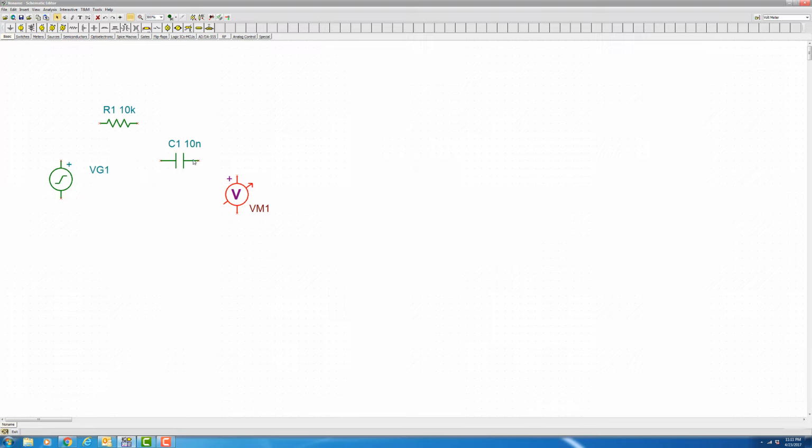It uses the last value that you picked, and I happen to use these for my tutorial, so I kind of cheated by preloading those values. But notice that the values are also in lowercase. One thing to remember is that SPICE, as well as any SPICE program like Tina, is case sensitive. So be sure that you always enter your values in lowercase.